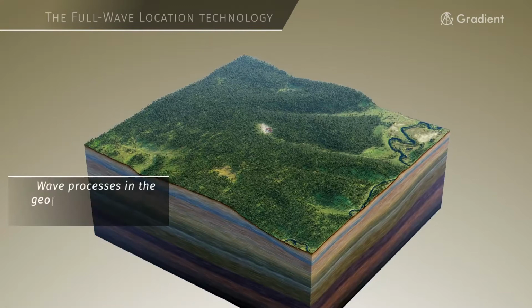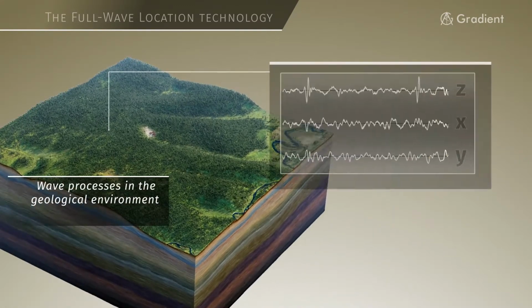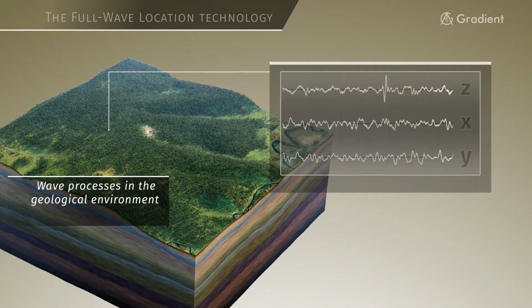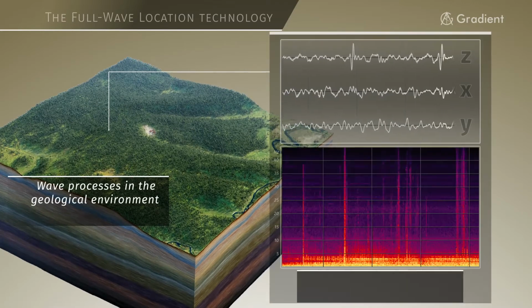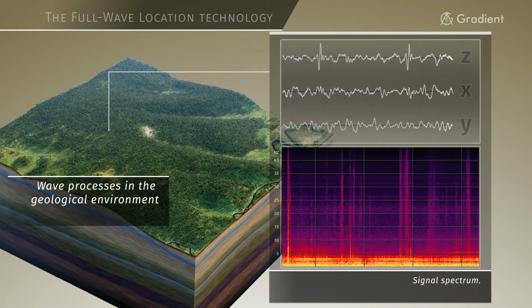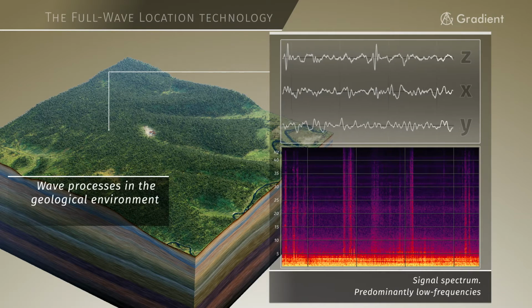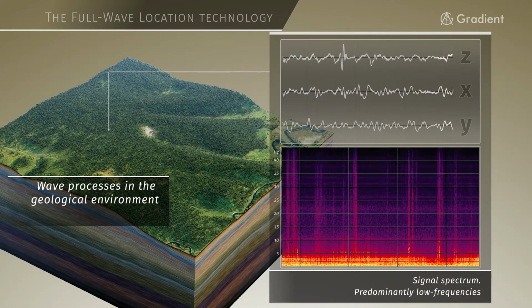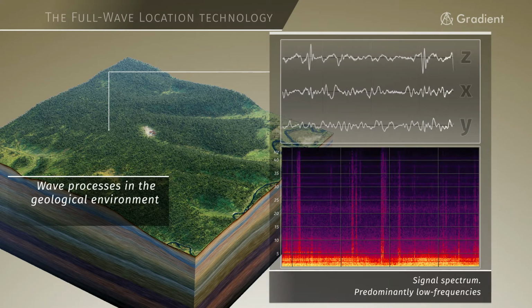The wave processes recorded during microseismic monitoring, due to reflections and attenuation in a heterogeneous geological environment, reach the surface in the form of a complex, low amplitude and predominantly low frequency response. To record weak seismic oscillations, highly sensitive, low-frequency three-component hardware complexes are used.